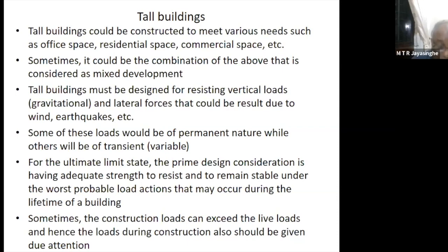It is not going to stop gaining strength in the first 10 days, because when you look at the cement composition these days, cement composition has changed a lot. 50 years ago, cement had 2 main ingredients that contribute to strength, in addition to the very important ingredient called calcium aluminate, which gives the initial strength, and is important only for the initial strength. But after that, there are 2 very important ingredients that can give strength. One is called tricalcium silicate, the other one is called dicalcium silicate.